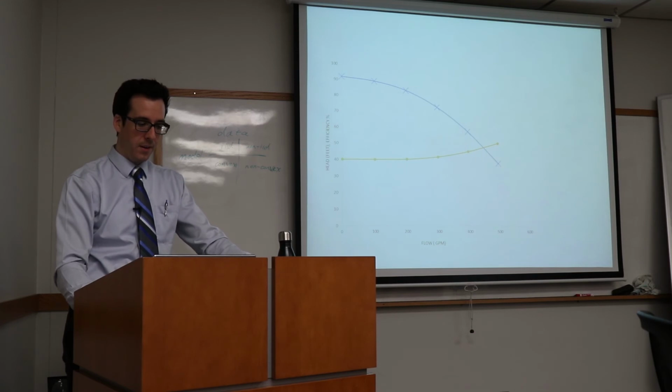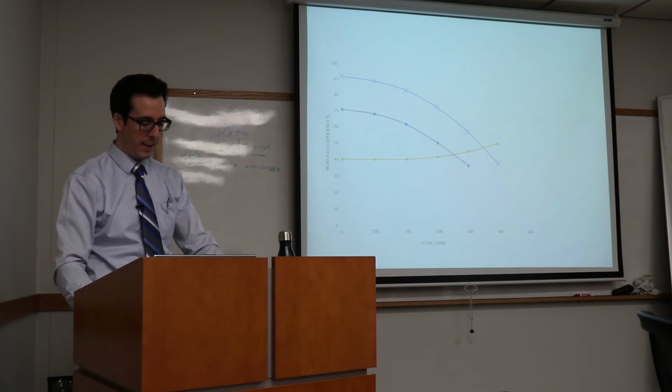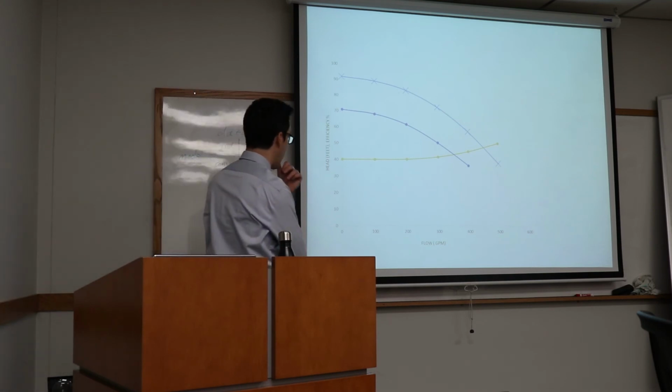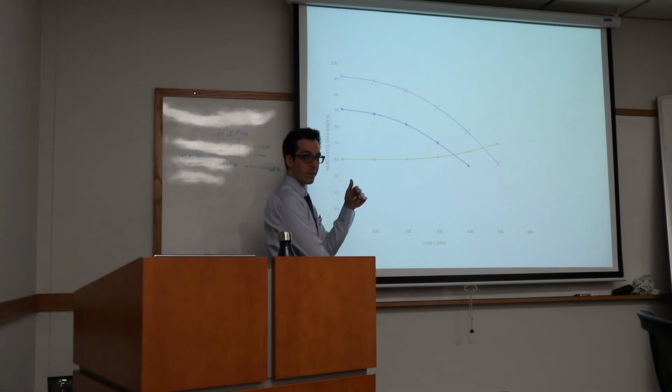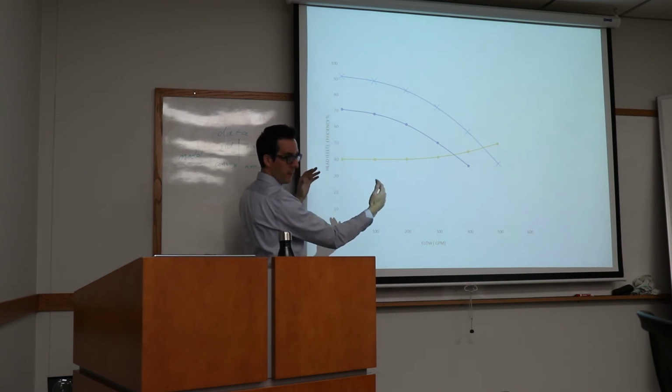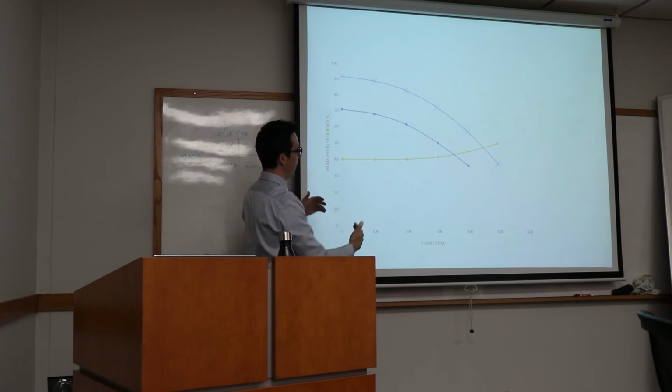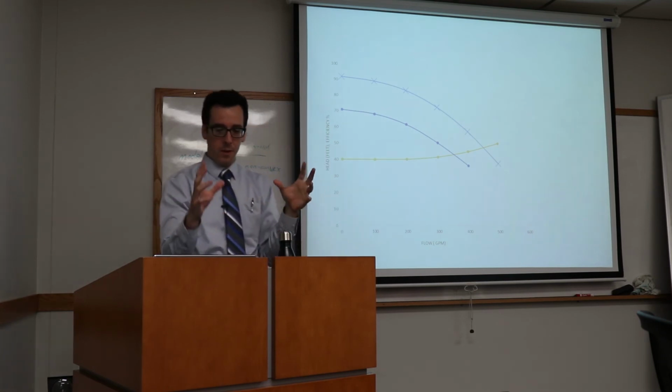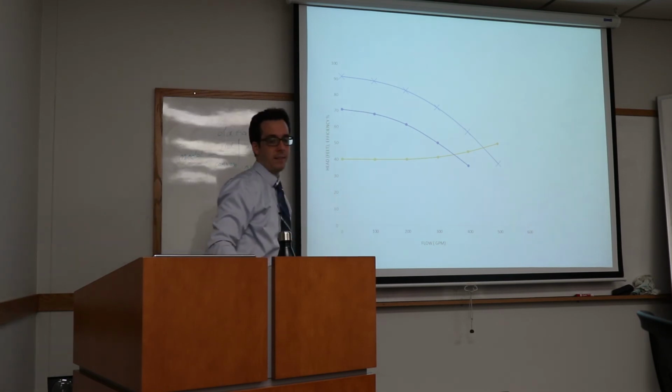We could also equip it with a VFD. That essentially shrinks the pump curve toward the origin, right? So for a certain pump speed, you just essentially copy the curve. There's a little bit of geometry involved, in affinity laws and so forth. But you shrink the pump curve toward the lower left.